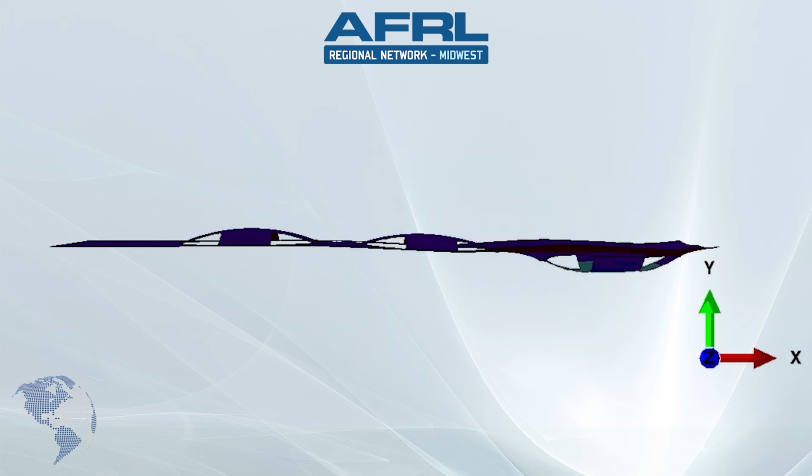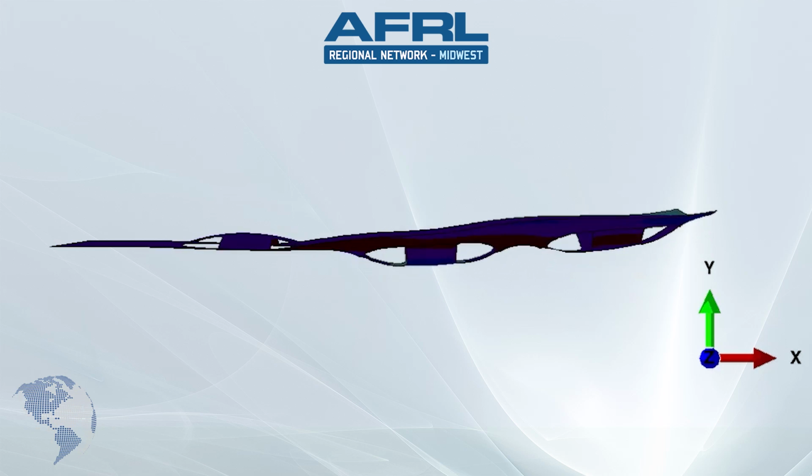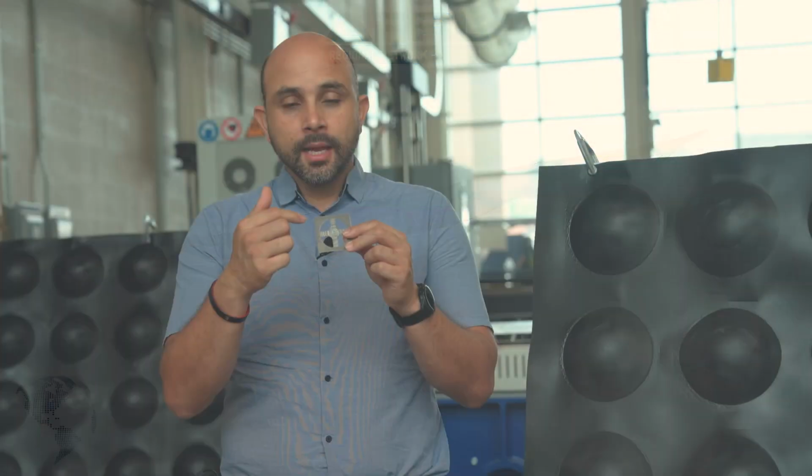We have further conducted analyses on the effect of introducing this geometry that has reduced strains on the global capacity for morphing of these metastructures, and our results show that we are able to still retain the morphing capability, which provides us with a good path forward to simultaneously reduce the stresses that are needed for snapping these structures, which allows for using structural materials and still match the desired level of morphing that we want to have these optimal shapes for different flight regimes.